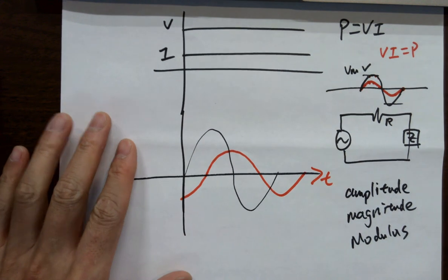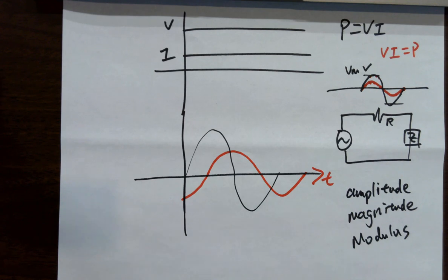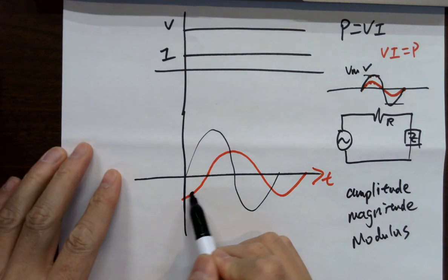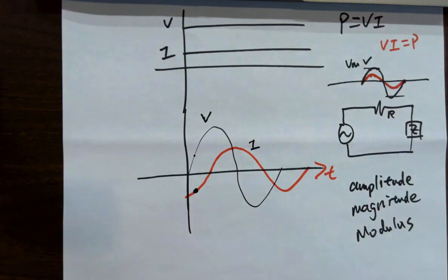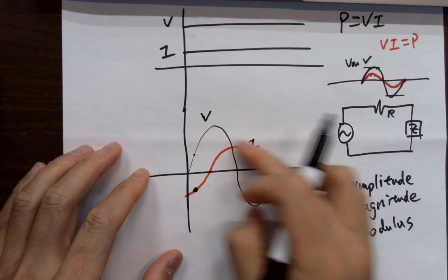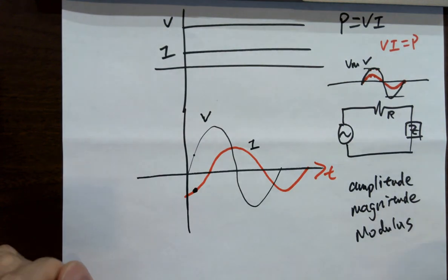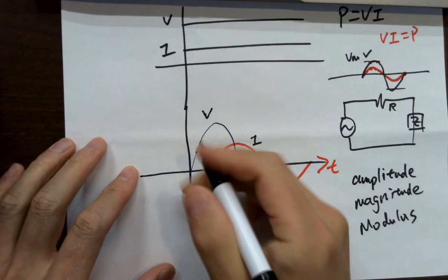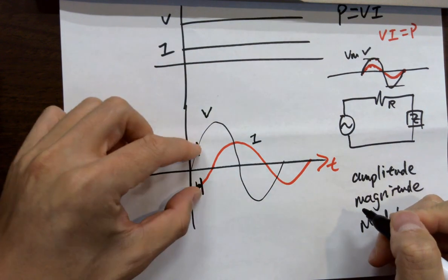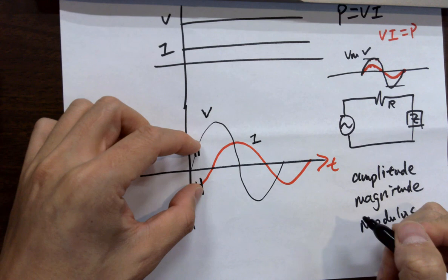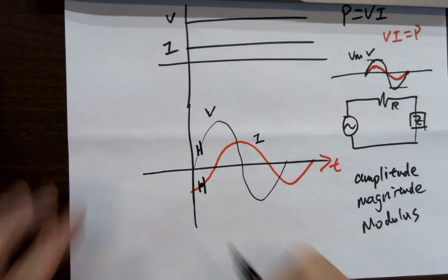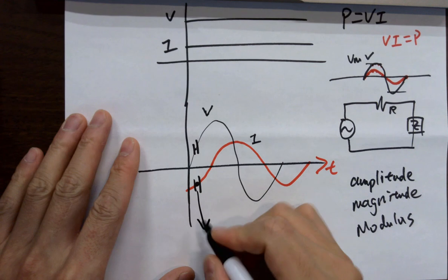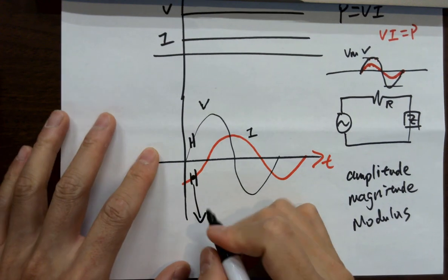But for this one, if you just look at time, because time is the dimension of this physical world, at this moment it has a certain current and certain voltage. This is I. So it does have a power consumption at the moment, if you treat these plots as discrete points. You agree with me? With a super short time frame, there will be a current value and voltage value, and voltage times I will definitely give you a power. So what's the name of that power? You'll see this term in your homework assignments, probably twice. Two of the problems are giving you that concept, but it can be confusing. So what is that called? The name explains itself. It's called instantaneous power.